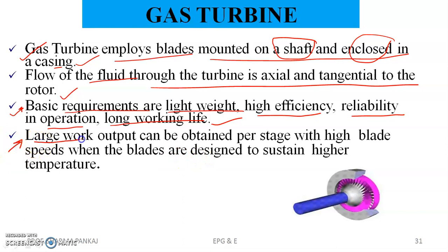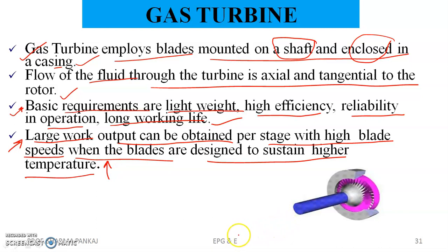The large work output can be obtained per stage with high blade speeds when the blades are designed in such a way to sustain higher temperature.